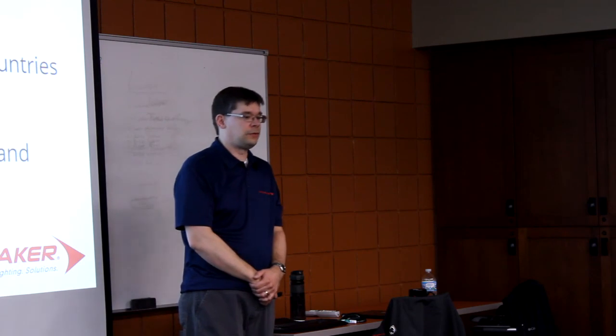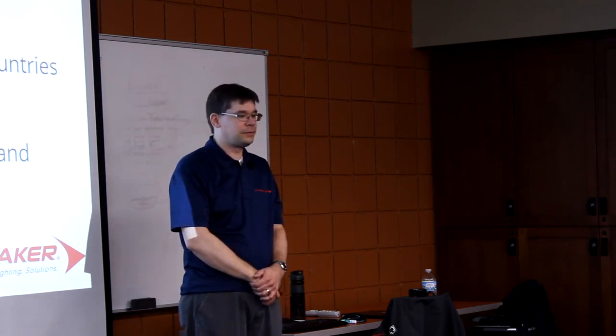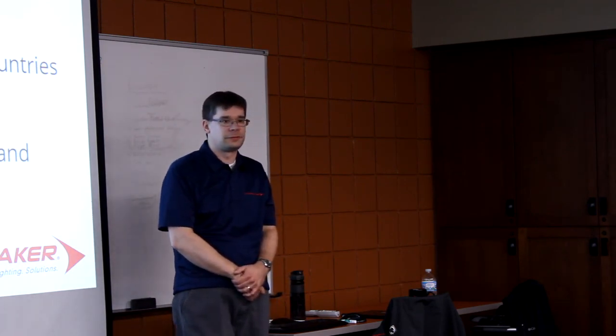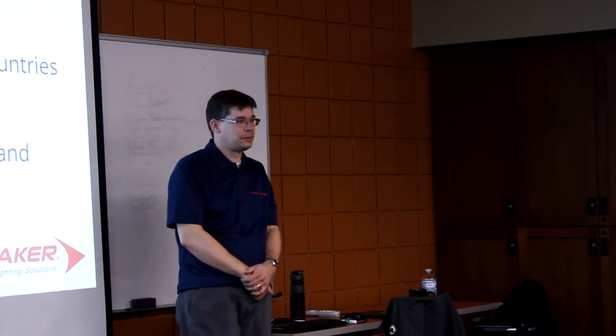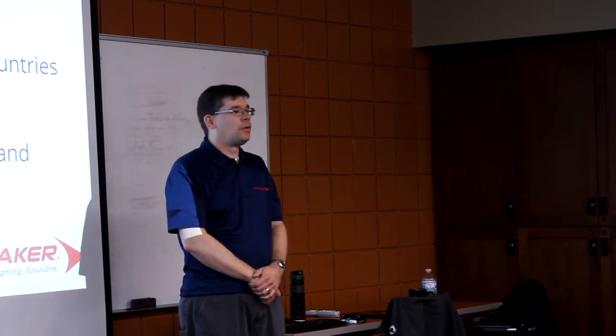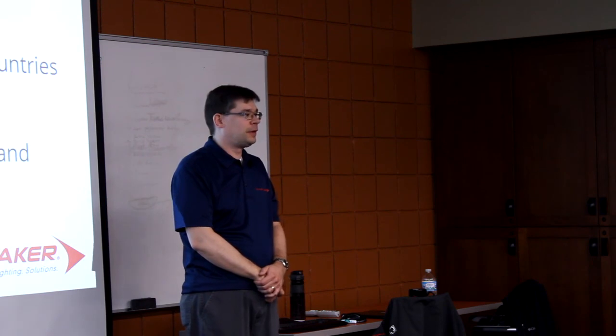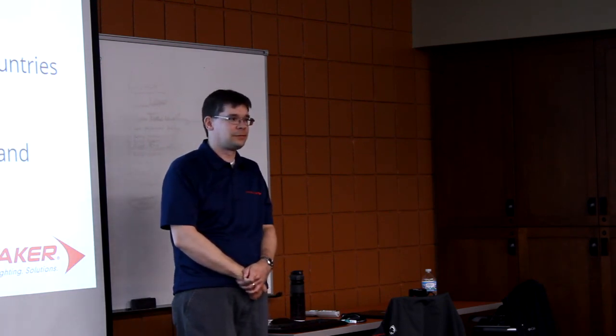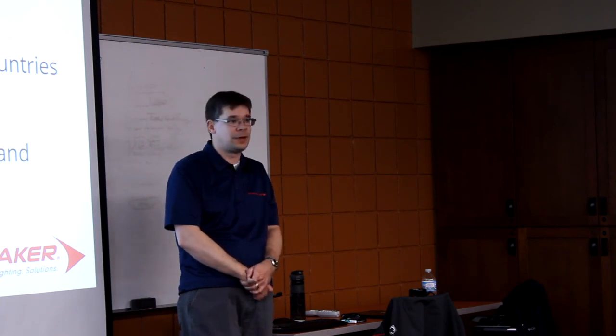So, as we said, FMVSS does not talk about LEDs because when it was originally written, they weren't there. Fortunately, the way FMVSS defines certain types of lamps, we're able to fall under a category called integral beam headlamps.